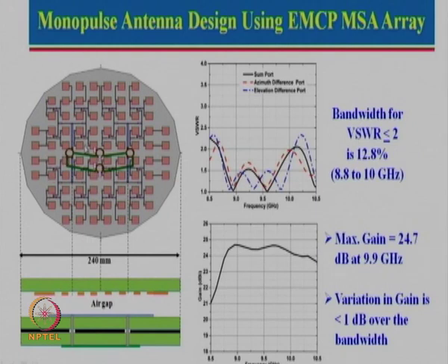Now as we mentioned earlier, when we were talking about a linear array, if you use uniform amplitude, side lobe levels are relatively high, minus 13 dB. But here what we have done is taken power from the outer one, which gives here. So this actually provides an amplitude taper, the center is maximum and it goes down, and this particular array also gives us a reduced side lobe level.